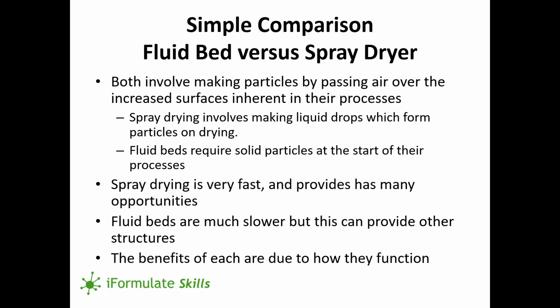So, as I said before, both processes benefit from having very high heat and mass transfer rates, because you're making either liquid small droplets or small particles inside a fluidized bed. Spray drying is very fast because basically the droplets fall down under gravity, and this has many opportunities for quick drying, particularly with materials that have very high water content.